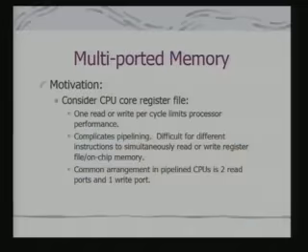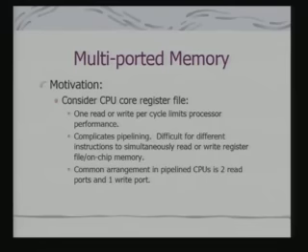If I have only one read or write per cycle, it can limit the processor's performance. It also complicates the pipelining, because it becomes difficult for different instructions to simultaneously read the register file or on-chip memory. So, a very common arrangement is for pipelined CPUs to be provided with 2 read ports and 1 write port associated with the memory.